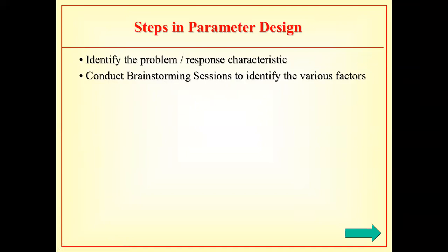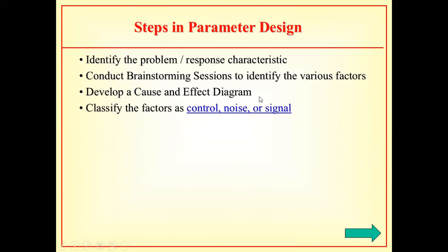Yes, turning also affects so many things. Coolant also affects, vibration affects. So many parameters are there. Make a combined list of the parameters. Once you identify all the factors, whether it is a controllable factor or an uncontrollable factor, make a list. Once you make a list, just for the sake of clarity, to see how these factors are related, you develop a cause and effect diagram, a fishbone diagram, or what some people call an Ishikawa diagram. Once you prepare the diagram, the entire thing will be visible and very clear to you.